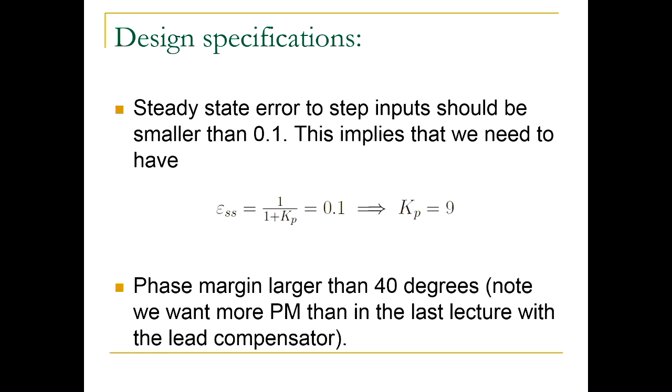So how would I achieve this? First, I'm saying, let me shift down without the compensator. So this thing here would be due to the compensator. But first I'm saying, forget about using the compensator. Let me see how much I need to shift this down so that I achieve the required, well, this is not drawn properly. So let's say that this is your maybe minus 180 degrees. So you have some phase margin here, required phase margin. So what I'm first asking is, so first I designed K to tick off steady state errors.